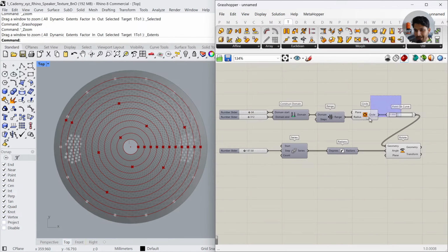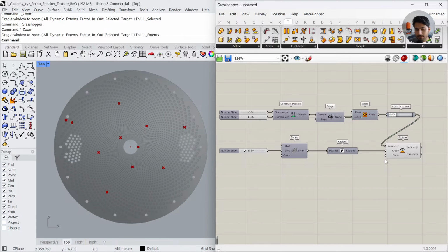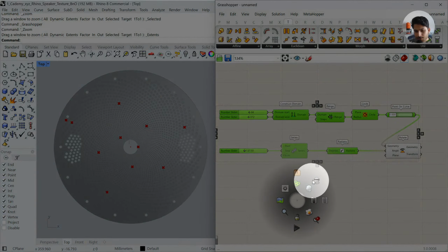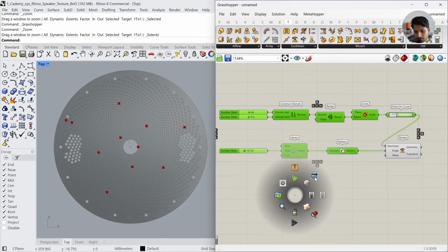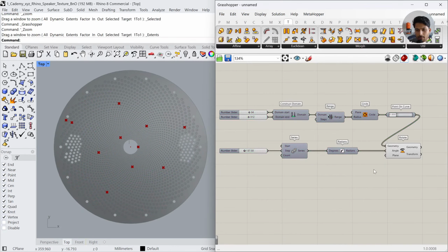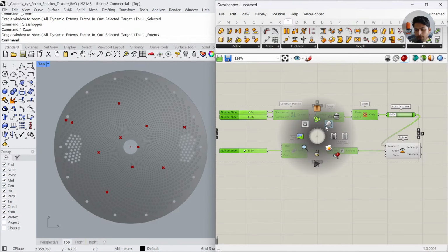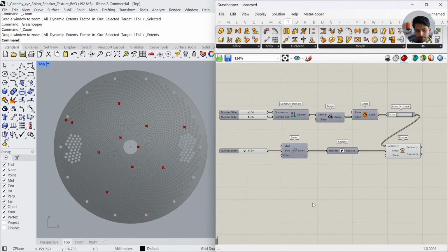In order to properly see it, hide the other nodes. Okay, so to hide other nodes in Grasshopper, you select the nodes that you want to hide. You press the middle mouse button, and there's this option to enable or disable the preview. Okay, on Mac, you can also press, I think, Option space together, and that is also going to launch this radial menu, and you can enable or disable the preview. Now you will say, this doesn't look like the Fibonacci sequence. Well, it's true because we don't have sufficient points, okay?